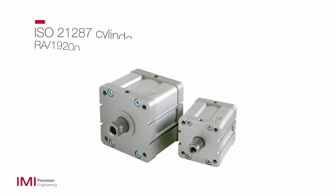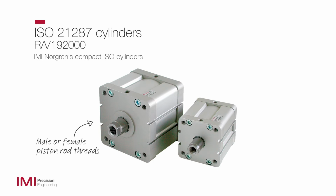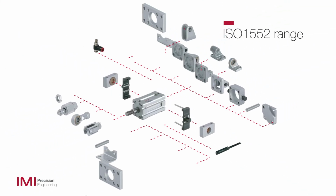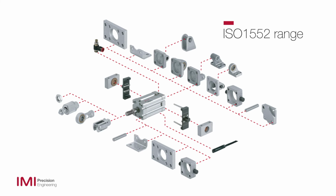This is IMI Norgren's compact ISO cylinder. Offered as either single or double acting with male or female piston rod threads, these cylinders have flush fit reed switch or solid state switches and buffer cushioning as standard. There is a large range of accessories for these cylinders.